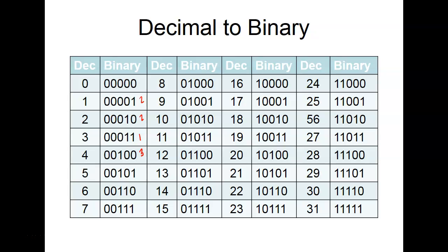So what would happen is that these binary counters have problems with extremely high speed devices. If I've got a motor running at 7,200 RPM and I want to use this as a position sensor, then there's no way in the world that that binary counter can keep up with that. So what they did is they came up with a code called the Gray code.